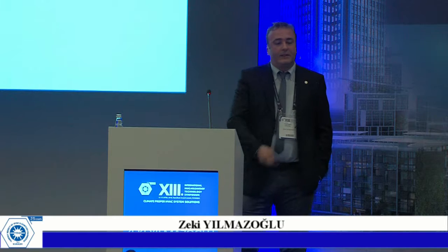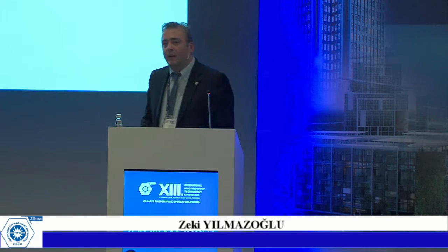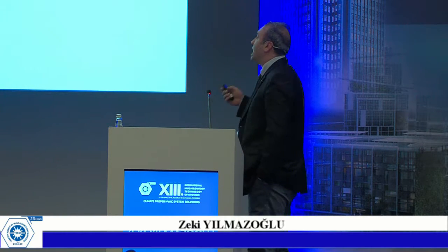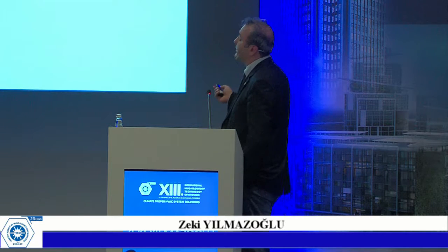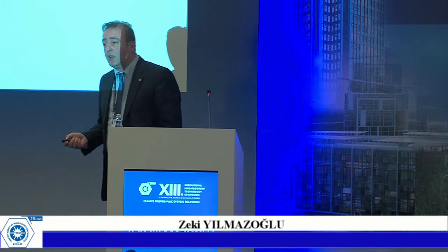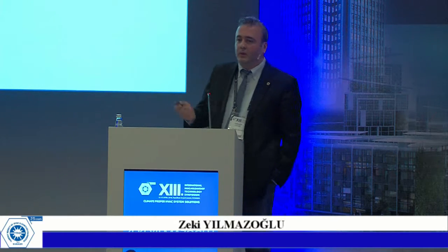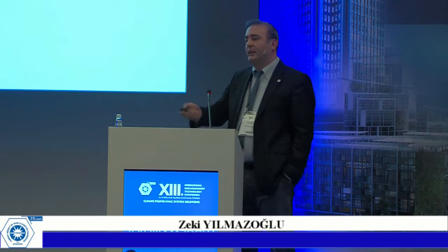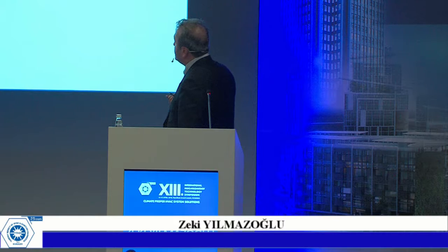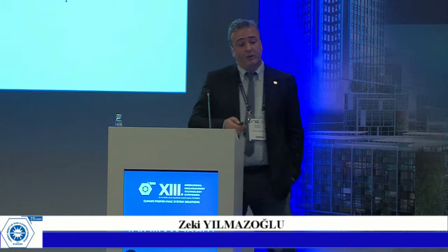As the presenter talked about on the first day, outside emission concentration has to be taken into account. If it is more polluted, there is no need to open your window or naturally ventilate the building. And in mechanical ventilation, the location of the fresh air intakes has crucial importance.